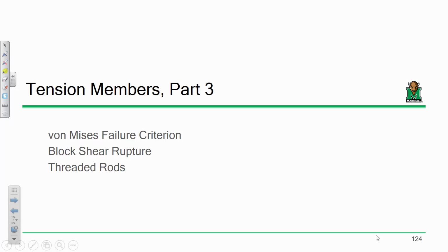Nowadays, like I said with integral abutments, we're using systems to try and head off those problems in the future. Because the market changed, the solutions that we are now using have changed as a result. We're trying to avoid that stuff in the future. So with an integral abutment, you cast the deck and the abutment integrally, you don't have that joint, so it's something that won't fail in the future. That's sort of the idea.